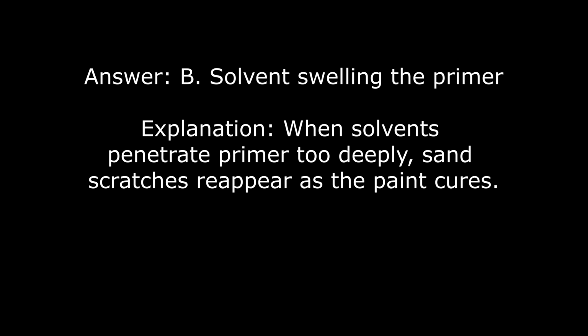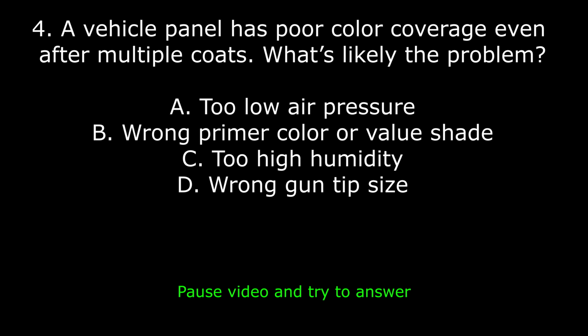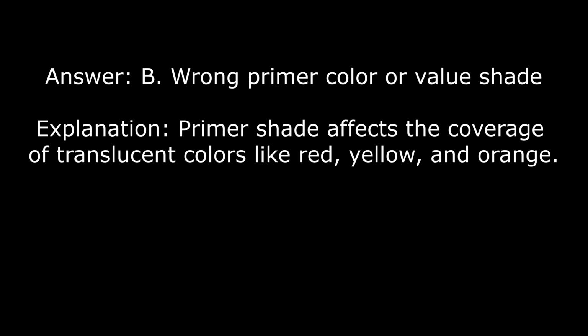3. What causes sand scratches to appear after painting? A. Using too fine a sandpaper. B. Solvent swelling the primer. C. Over-curing primer. D. Incorrect reducer. Answer: B. Solvent swelling the primer. Explanation: when solvents penetrate primer too deeply, sand scratches reappear as the paint cures.